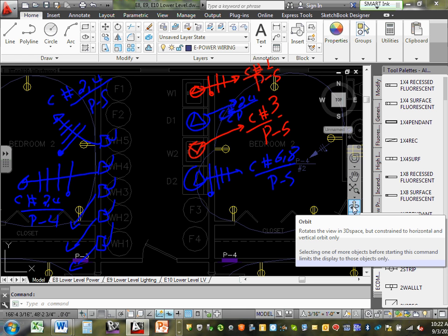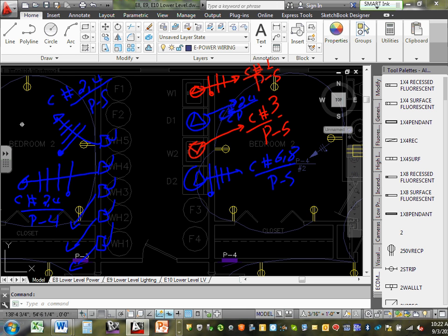So how many conductors for the dryers are you going to have? You're going to have 3 conductors, 2 hots and a neutral, and a ground. 3 conductors plus the ground. Because everybody knows what we're doing. This is going to be my dryer. Why do I know that's going to be 4 wires?